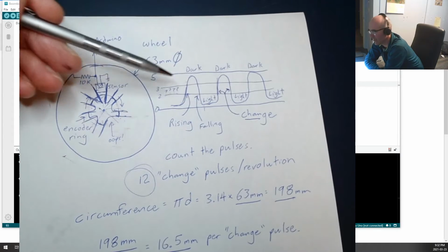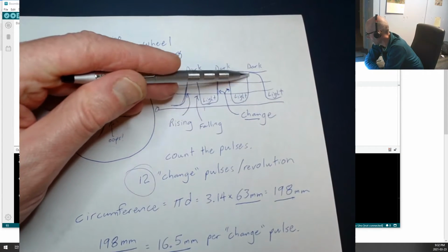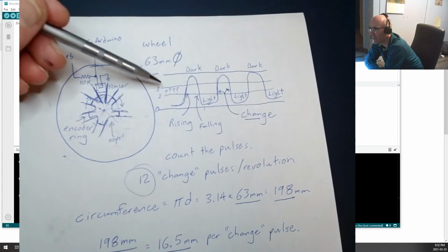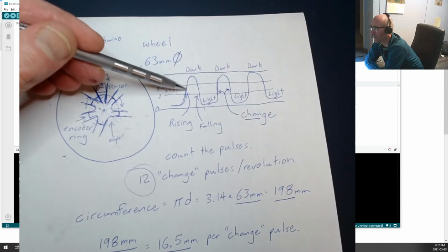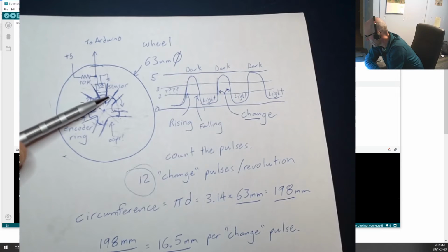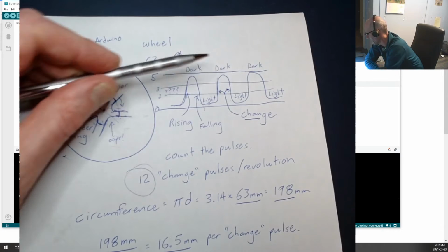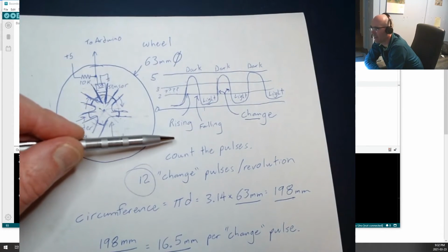And then the next part of the encoder disk will come along and it'll be light again, it'll go low and it'll go high. And we should see a nice little pattern coming along like this. Now I've drawn it as a little bit of a curve right here at the top, and we'll take a look at it using your oscilloscope to see why it's curved at the edges. As this edge comes along, it starts to get a little brighter and then it starts to get a little darker, which is why we've got the edges kind of rounded off like that right in there.